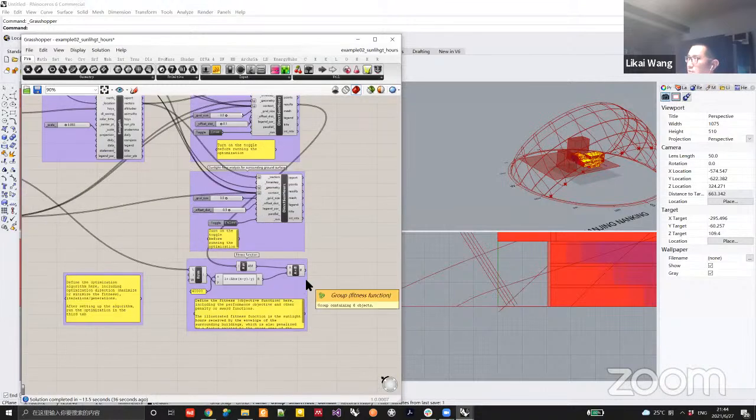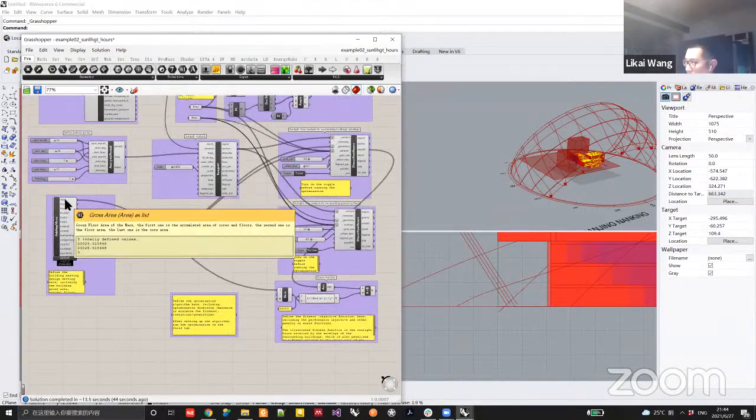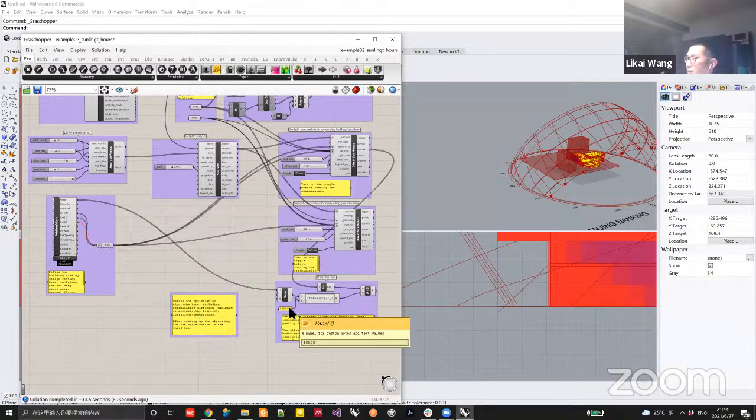If you have seen my tutorials on YouTube, usually I make a soft constraint on the floor area, because the generation will occasionally produce crazy designs that cannot satisfy the functional requirement of the gross area. So you need to set a gross area to ensure that all the designs generated by this optimization can satisfy the needs of your design project.